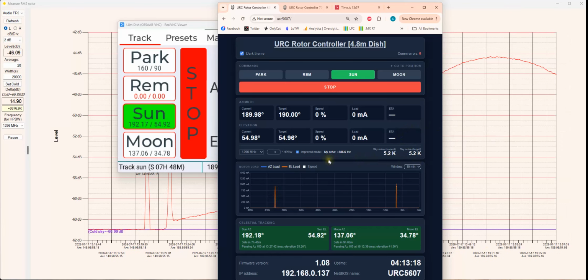If you can get the antenna to track in elevation, it will be the best, because you have the most clean sweep. Then the sun is passing the antenna right from the side and leaving it at the other side without any change in elevation, as the dish is following the sun's elevation.